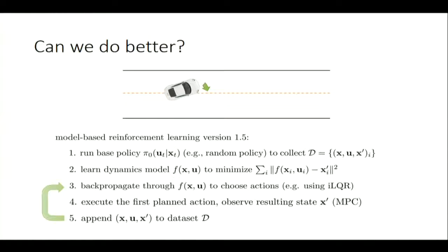This is what we saw last Wednesday, if you remember the video with the funny humanoid trying to get up. This is model predictive control, meaning every time step you replan your actions and you only execute the first one. And that way, if the next state that you get from executing that action is not exactly the state you expected, you will replan, you'll compensate for that drift.